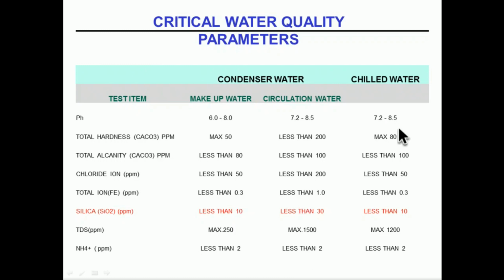based on that. Then we also have chilled water, because chilled water is the one which is generally neglected. Scale is one indication in condensers. Yes, that water is scaling and alkaline, so people will take care of it with treatment. But in chilled water, unless it fails or something, we don't come to know.